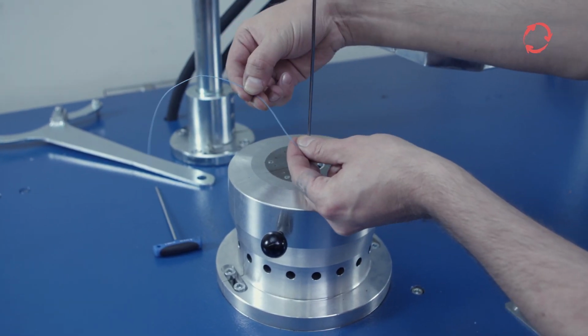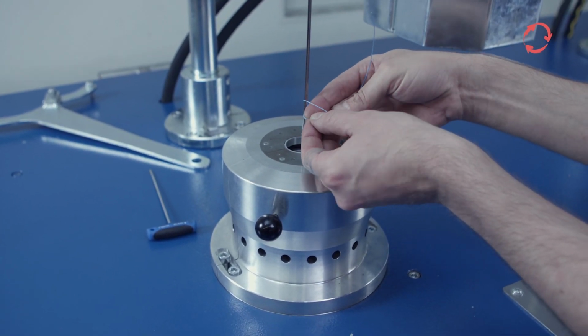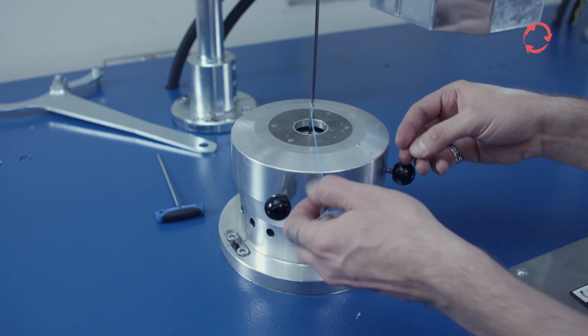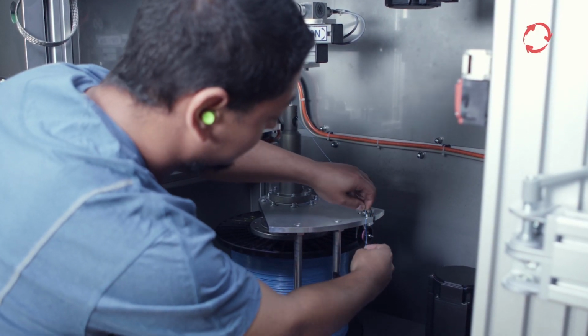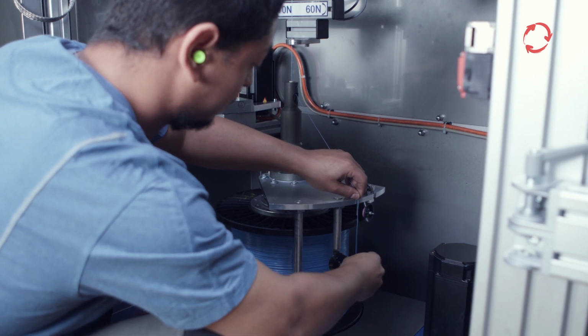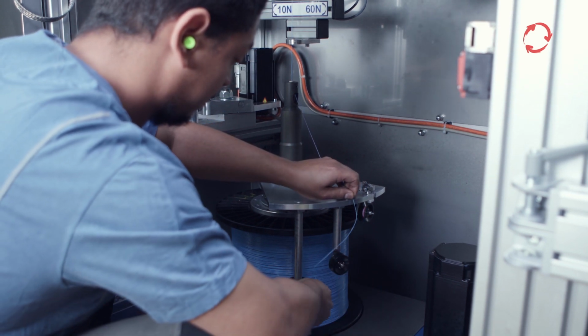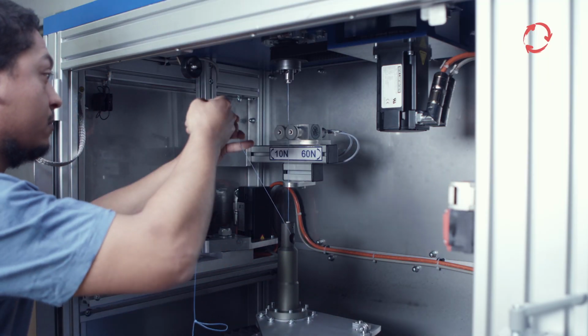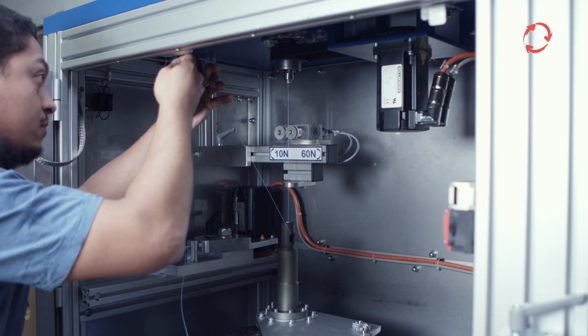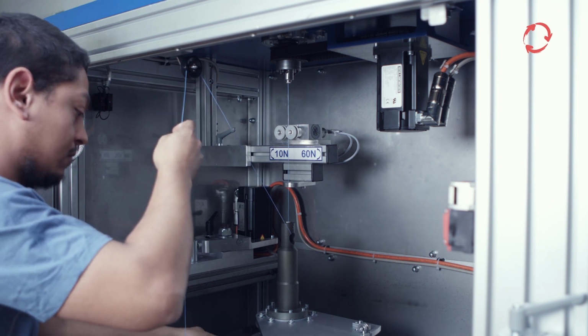Tie the spiral thread to the spiral mandrel. Then wind the wire on the outermost deflection roller of the winding plate back to the coil. Then pull the wire over the deflection roller mounted under the machine table top. Now cut the wire about 50 cm below the upper deflection roller and knot the end into a loop.